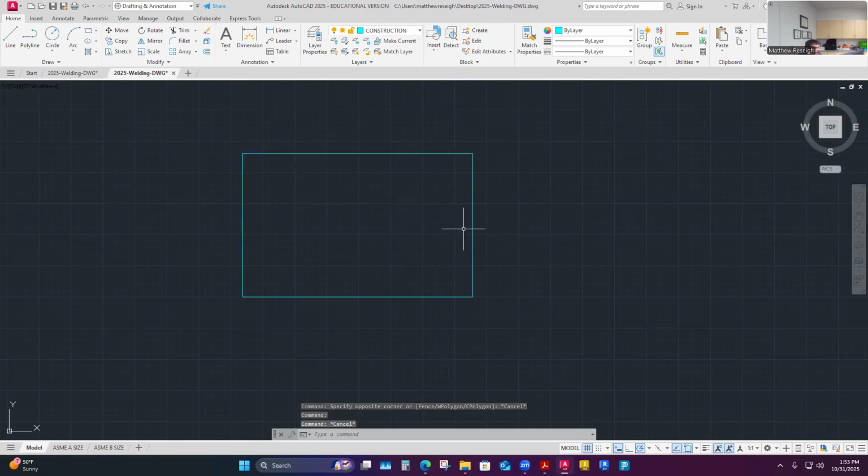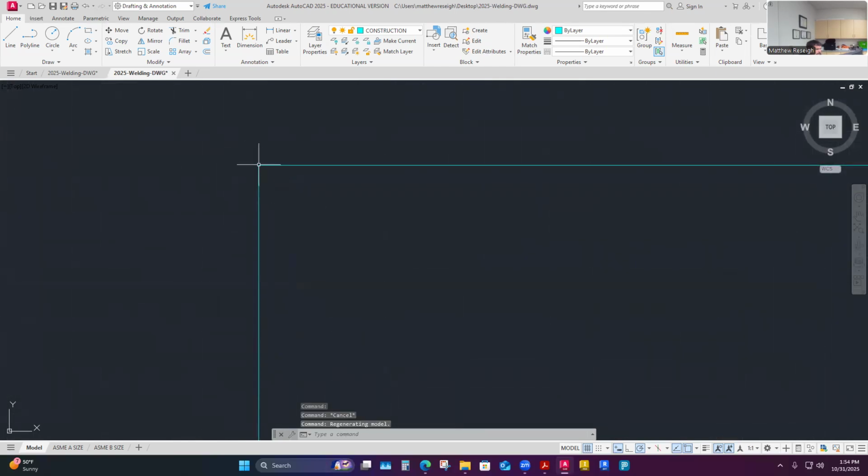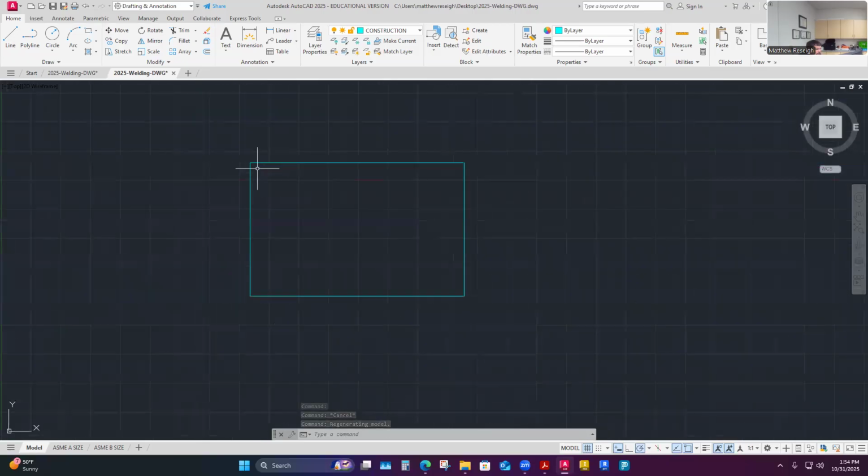And it's all individual lines essentially, right? These that show up when I highlight and click on them are just the grips that are associated with it. I think I said this before in one of my videos, that geometry has different grips. Lines have a midpoint and endpoints that you can grip and snap to keep things accurate. So a machine can cut this because it's hooked up to itself line for line. There are no spaces between these. The nature of these grips, the object snaps, and how we draw is that we want to hook everything up without any breaks in it,